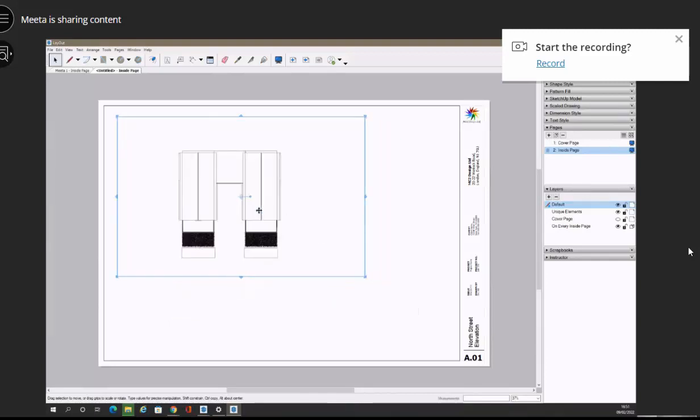Layout and SketchUp are linked, so if you make any changes to your SketchUp model once you've brought it into Layout, you can still update it and Layout will update it automatically. So if you've changed a texture, or made an extension, or gotten rid of some part of the building, when you launch Layout, it will tell you that there has been a change to your SketchUp model. You can update it from there, and Layout will automatically update all your files within Layout.